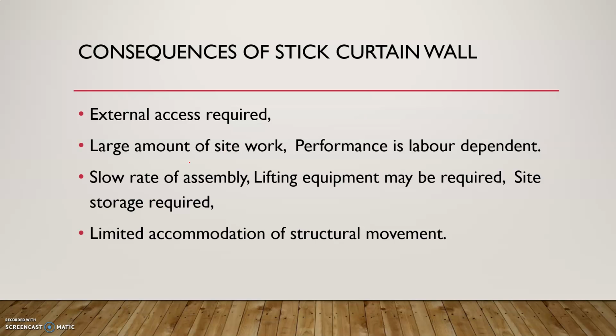Consequences of stick curtain wall. So with stick curtain walling, we need external access, a large amount of site work, and performance is labor dependent. So you have to have good workmanship on site.